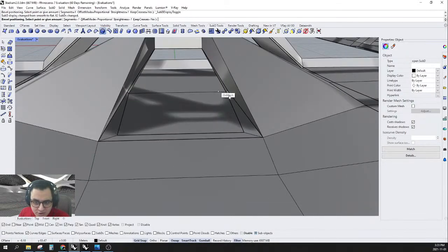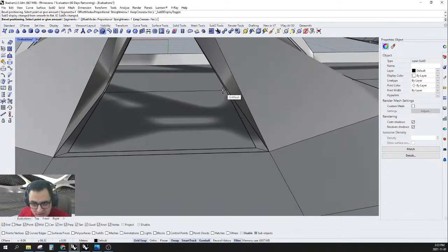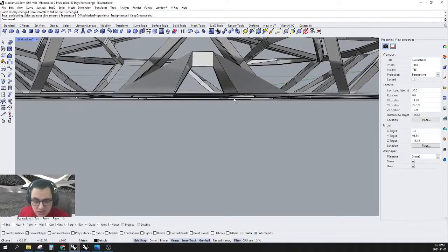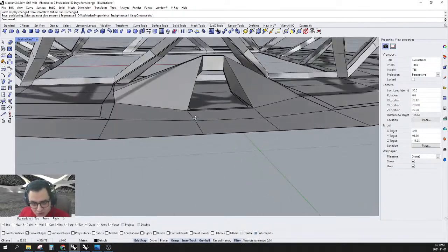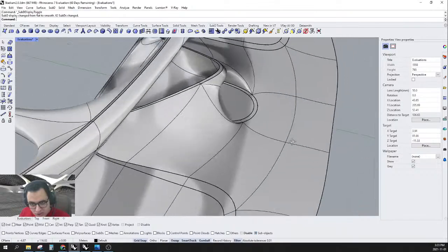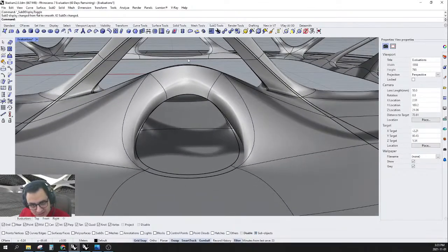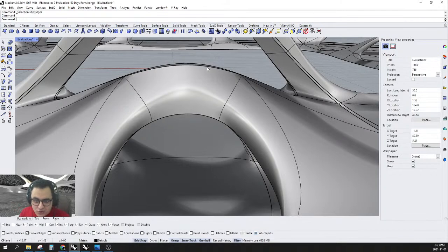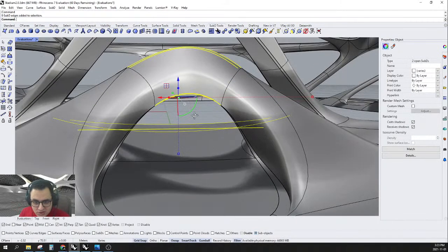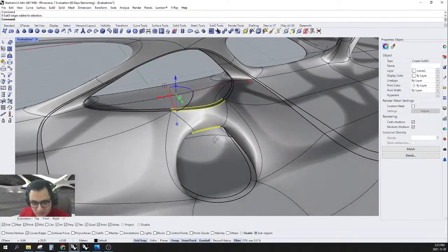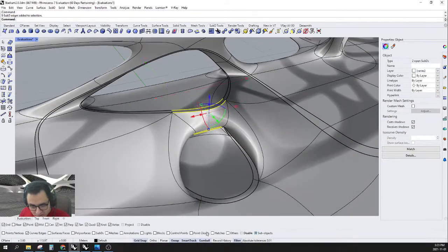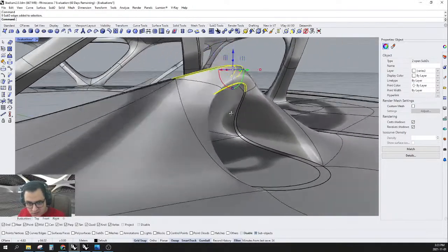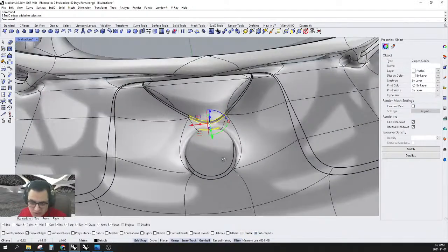Why is it beveling so much? Okay, yeah, something just like that. Again, this will have a little bit of an issue, but we will fix it. But for now, it will look something like this. This is too thick. Sorry, this is too thick. So I will simply select those curves right in here and ignore these, and click on the gumball twice and maybe 0.5. Okay.